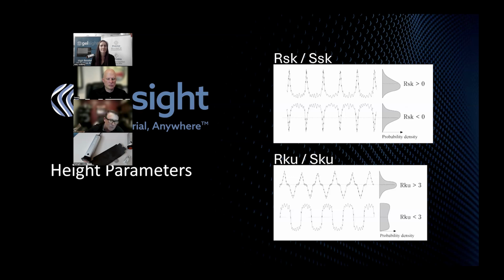And then there's a whole other family of parameters that can take that plateau hone surface and compute even more detail. Kurtosis is very similar to skewness. It comes from the world of statistics. It basically tells you, for lack of a better term, the peakedness of your profile. As you can tell from the skewness, the kurtosis value of that top profile is larger because it's got kind of spikes in it, and in the lower profile that they're more rounded off, the kurtosis value comes down.